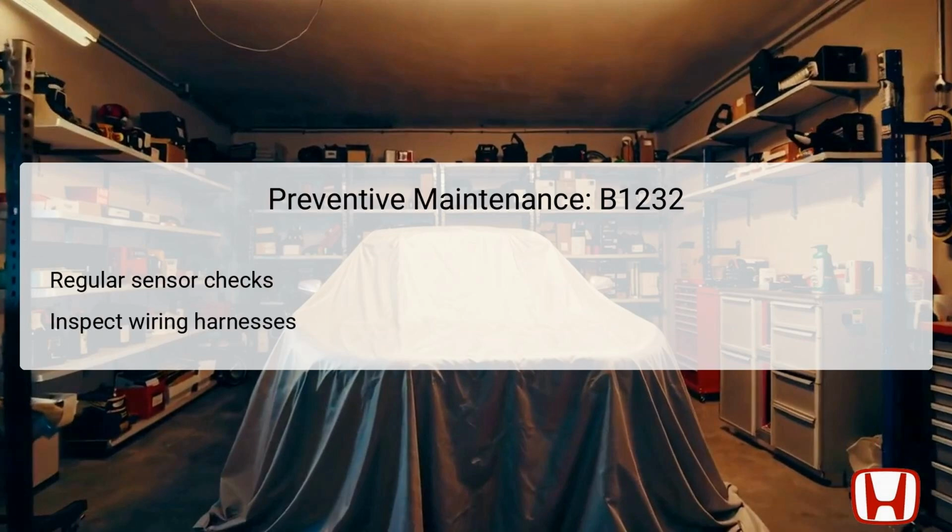Preventive maintenance plays a significant role in avoiding DTC B1232 and similar HVAC issues in the future. Regular checks of the evaporator temperature sensor should be conducted to ensure it is functioning properly and remains free from debris or physical damage. Furthermore, inspecting wiring harnesses for signs of wear, corrosion, or fraying can prevent short circuits that might trigger this code.